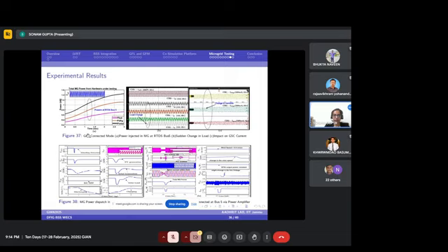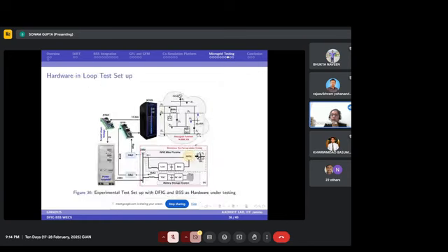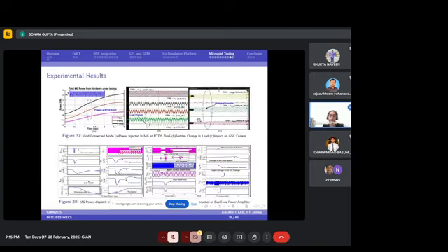Within this grid connected mode, these are the powers from the battery, the DFIG, and the total power, which is going back to the RTDS, because in the network we can see that at this bus the battery storage and the wind turbine are connected. So the total power also represents the power coming from the battery and this wind turbine as well. Whatever it is generating, that generated power will be fed back to the network also.